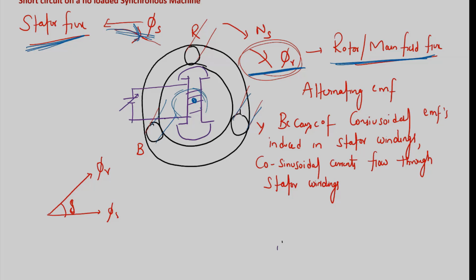Now, armature reaction is the impact of stator flux on the rotor or main field flux.